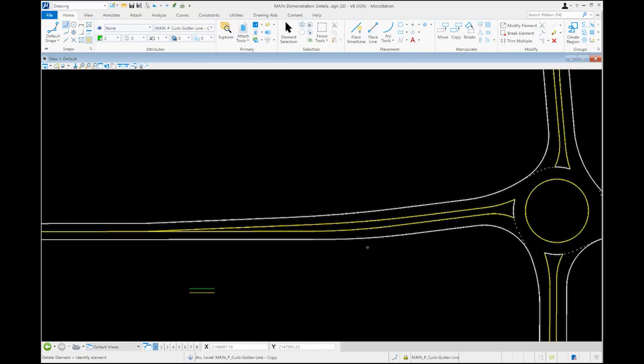Section 3.10 of the GDOT Roundabout Design Guide identifies that the splitter island length is going to vary based on the speed context. And for this example, we have a 50-mile-an-hour posted speed along this east-west roadway. For speeds above 45 miles per hour, the guide suggests a desired splitter island length of about 200 feet.